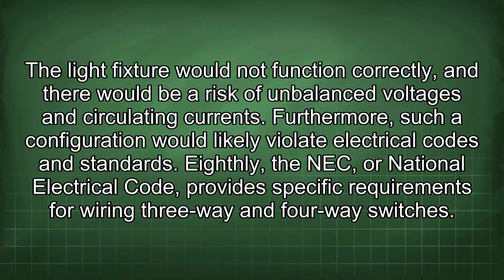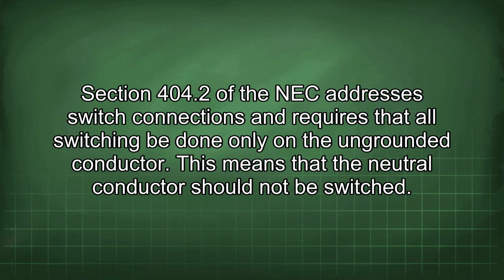Eighthly, the NEC, or National Electrical Code, provides specific requirements for wiring three-way and four-way switches. Section 404.2 of the NEC addresses switch connections and requires that all switching be done only on the ungrounded conductor. This means that the neutral conductor should not be switched.